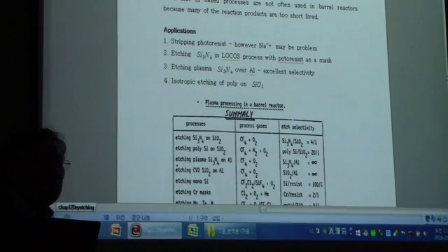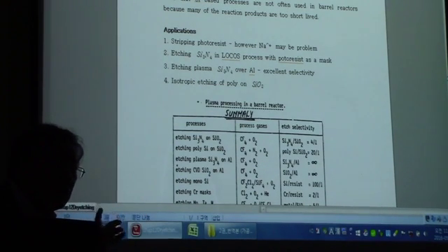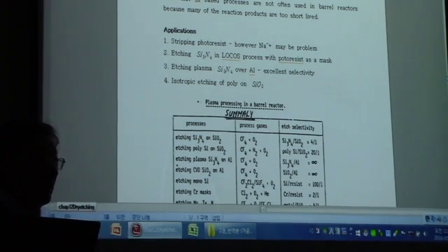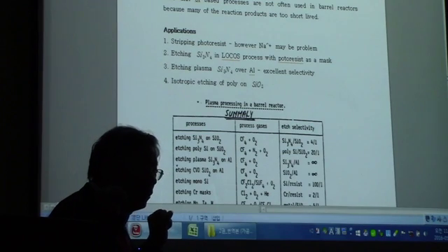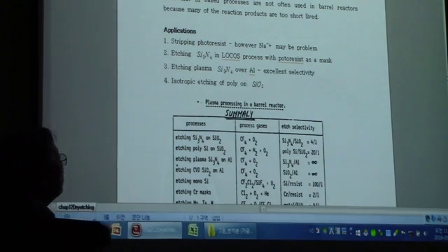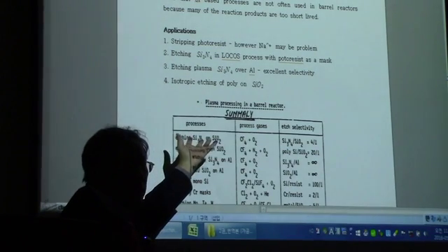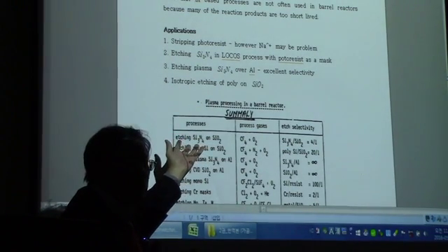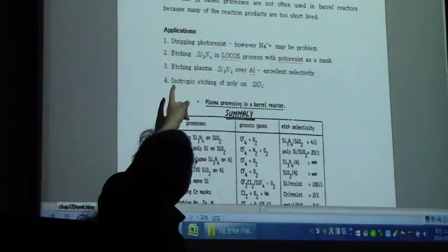We used wet etching. But as we discussed, the disadvantage of wet etching is that it has many contaminated chemicals to be wasted, right? So in a recent VLSI process, we use dry etching for the photoresist stripping. And for that, the barrel type reactor is the most suitable equipment.